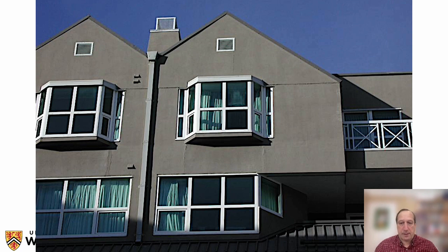I don't want to say that this is something unique to New Zealand. It happens all over the world with modern buildings that are designed without due consideration for deflection, the first of the 3Ds. Here we have a building in Western Canada where you have the slope here. They didn't hide it with a bit of a parapet, but instead they stuck a chimney right in the middle where all the rain would run. So they had to come up with very complex piping and flashing to direct the rain, and happens to be snow as well, around, which is just begging for failure. Possible, but way high-level stuff.